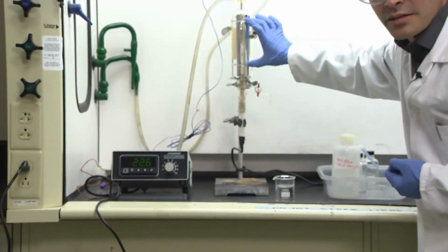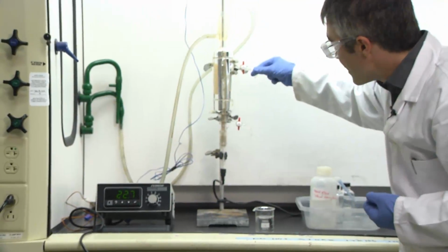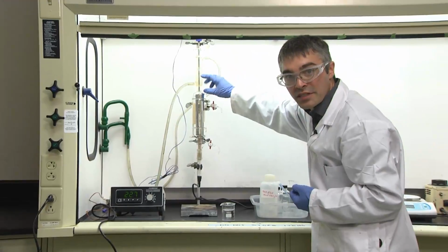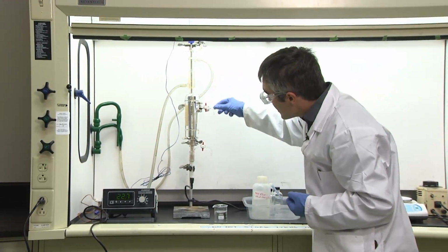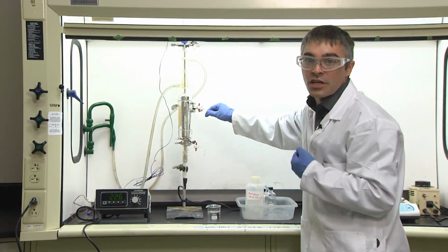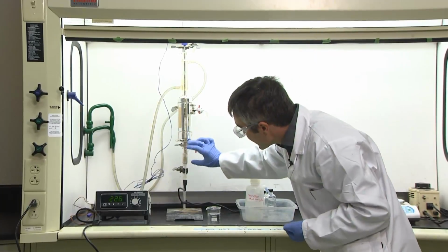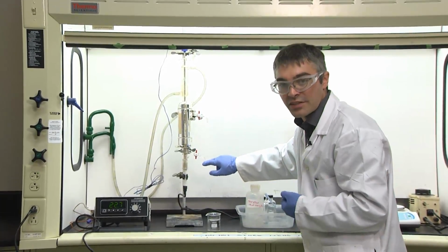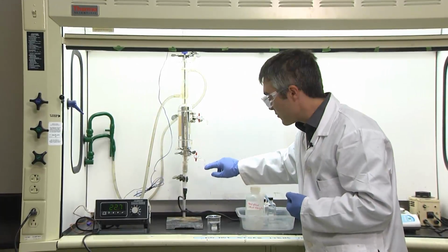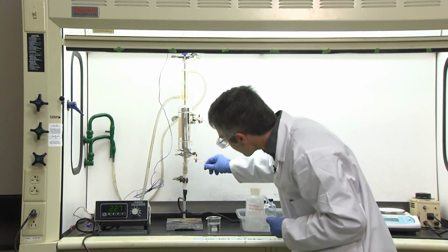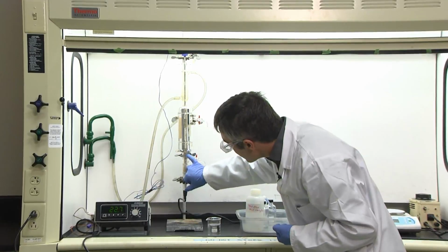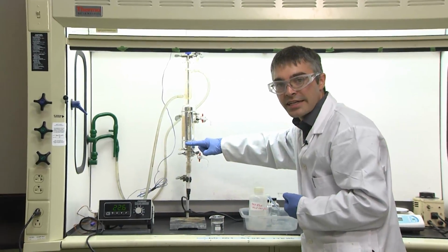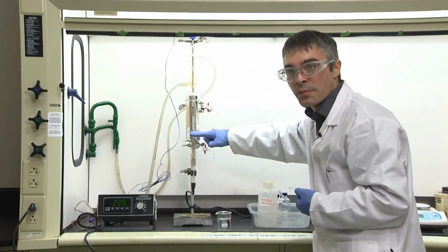Next, we have our vapor collection area, where we have our vapor collection sample port, which will collect the distilled sample from the condenser, which is how we'll be able to determine the concentration of the vapor. And down here, we'll have our liquid sample, where we'll be able to detect the concentration of the liquid by assessing the refractive index of both. Finally, our heater comes up to about here. At all times, this must be covered in liquid during operation.